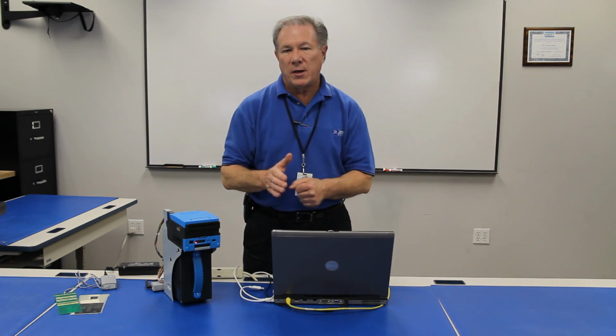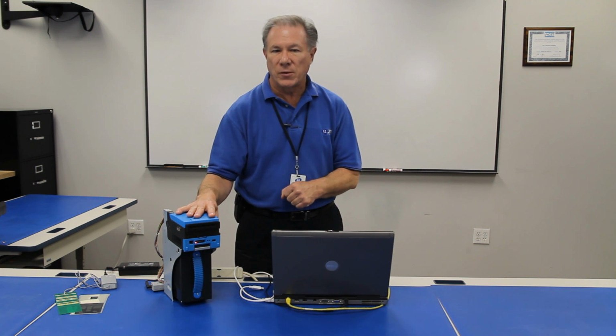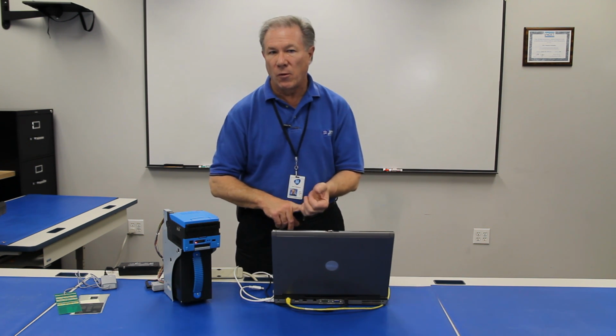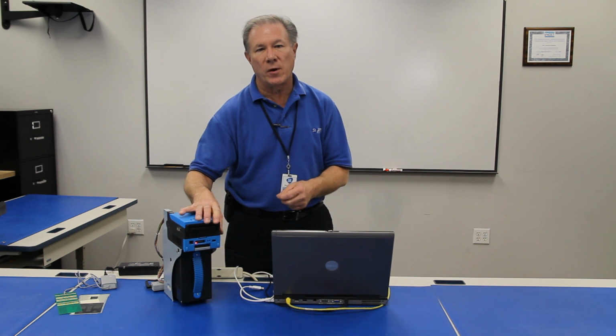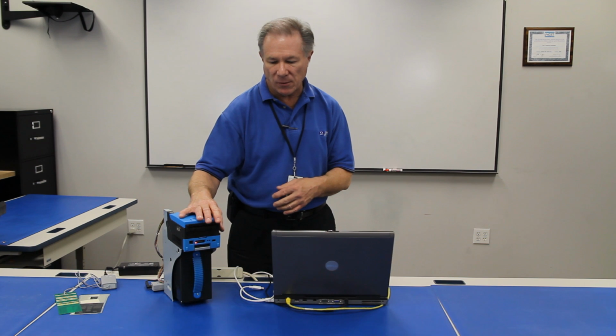Most of the time, you do not need to do a forced download mode, but there are times when you'll have to do a forced download. If you have a brand new processor board, you will need to do a forced download. Also, on some game platforms, if you're updating software on the validator while the validator is in the game, you'll need to do a forced download.